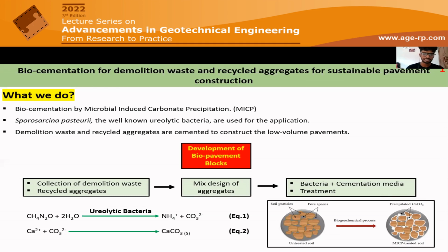The next important point in our study is the demolition waste. Generally, it contains a mixture of different materials, but we are focusing on concrete aggregates because previous studies confirm they have the capability to replace natural aggregates. Due to that, we collected concrete demolition waste from our environment and recovered it into different sizes of particles. Then we prepared a mix design for the concrete aggregates and packed those samples in cubic molds with different mix designs.